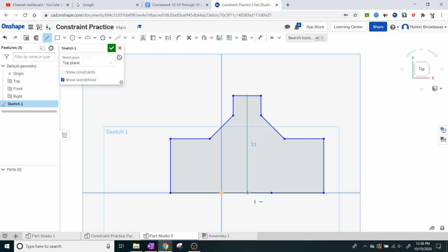The good news about Onshape is that it does snap to the halfway grids, although I did pull a really big dumb and I made these two parts down here parts of two separate lines. Oops. That's probably not the smartest thing to do, to be honest. You wanted that thing down the bottom to be one line. If you can get rid of that vertex by dissolving it or something, that would probably be the best thing to do. So I'm going to delete this sketch entity and see if I can move it all the way over here. Ooh, okay, there we go. So I have gotten rid of that one, and I probably wanted to do that.